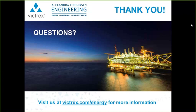Great. And then finally, I think we should make time for just one more question. Did you perform any thermal analysis of the tensile specimens after aging to see if there were any trends? After tensile testing, we have, as I showed, done various kinds of grinding them up, dissolving them in sulfuric acid, and measuring residual viscosity, which gives us a feel for the molecular weight change.